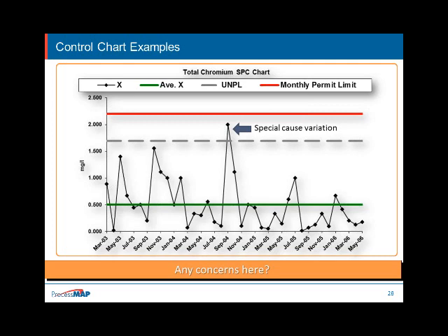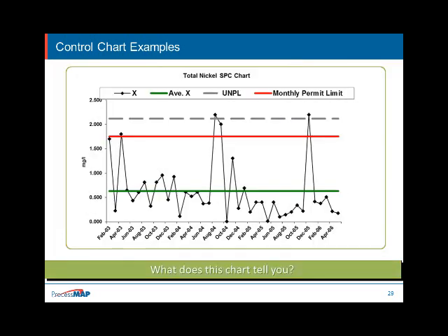Now, from a wastewater treatment plant, when you do your root cause analysis, there's a lot of things that may have happened. Maybe your chemical ads ran out. Maybe you have a brand new operator and he wasn't sure how to run the system. Maybe the sand filter failed. Maybe your flocculants ran out and you didn't get enough flocculants in that batch. Until you figure out what happened, find the root cause and put in the corrective actions, that can continue to happen and cause you a lot of problems and a lot of heartaches in this world. And trust me, folks, I've been there.